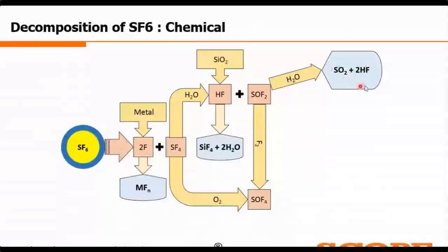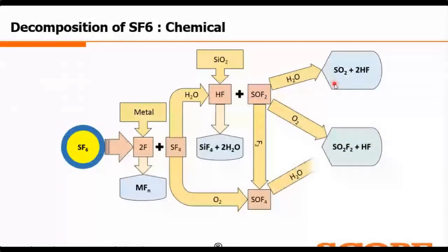So these are again stable byproducts, and in the IEC or the IEEE guidelines there are limits defined by the relevant standards. Now SOF2 with oxygen will form SO2F2 and hydrogen fluoride. The same reaction happens with SOF4 and moisture. So these are the stable byproducts.